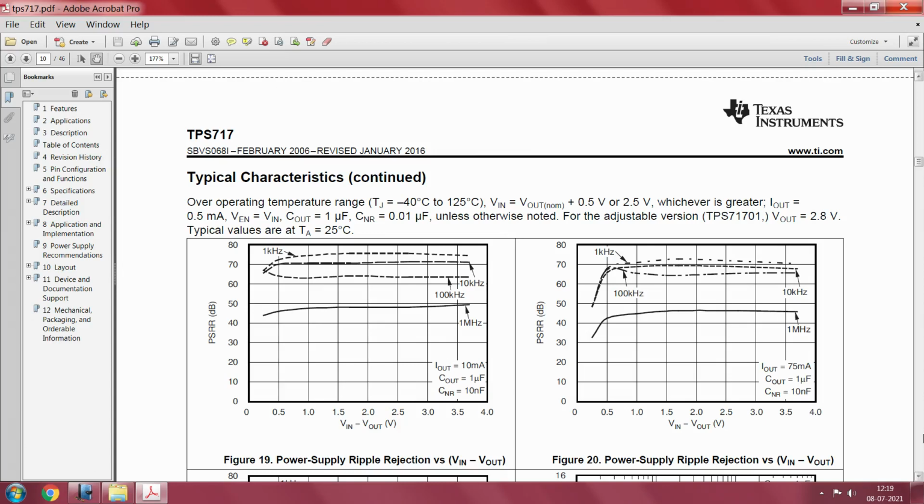The junction temperature comes directly from the fact that if the current consumed increases, the heating of the IC also increases, and it adds to the ambient temperature, a rise in the ambient temperature and also a rise in the junction temperature. That in turn has an impact on the stability of the LDO itself, right.